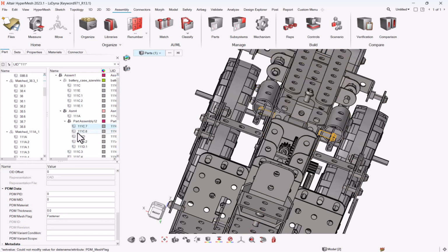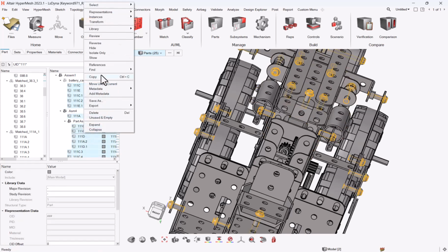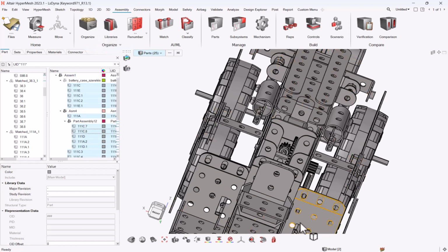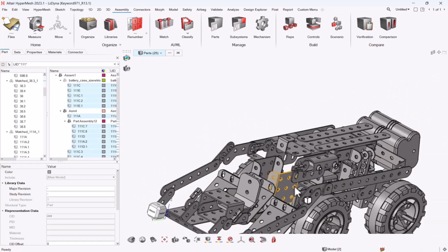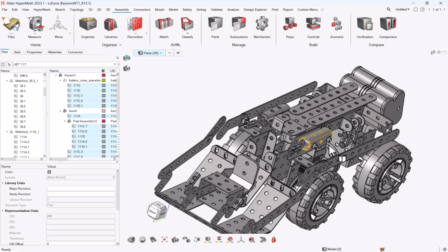Here it is, fastener. So I can select again, Control A my part, hide them, and do again the show and show. So strategy number 2 was about the part name. There's still a couple of parts. I want to get rid of small parts before getting to the next step. So let me pause, and once I've cleaned the remaining screws and some bolts, I will continue with strategy number 3.